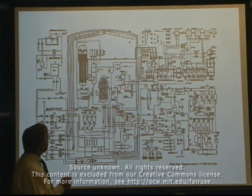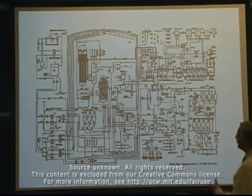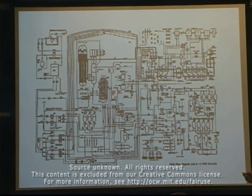And so once we start thinking about breaks in the main coolant pumps, pressurizer relief valves not opening, sources of water, makeup water, we'll work through this because I think it will give you an appreciation of the dependencies of what we might call the non-safety systems, like these turbines, to the ultimate heat sink, ultimate heat removal of this reactor. And once you get that feeling, I think you will have gotten what is needed to be gotten out of this course.